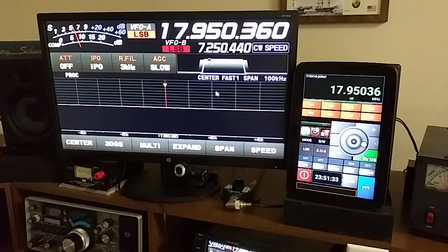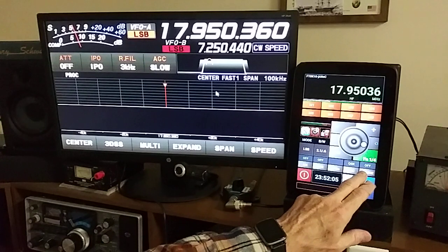One of the things about the Yaesu and some other radios as well, particularly when you're running them with an auxiliary external tuner, the power output sometimes during the tune cycles is not enough to initiate a proper tune. In the case of the DX10 here, the power output is about 10 watts, and when driving my MFJ tuner, the 998, sometimes when you're changing bands, it's just not enough to get a simple tune with the tune button here. Well, the M-Tune solves that.